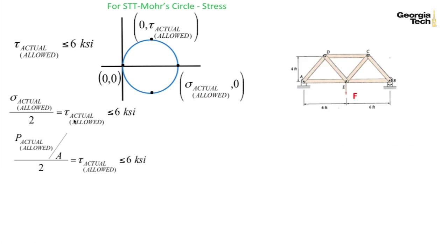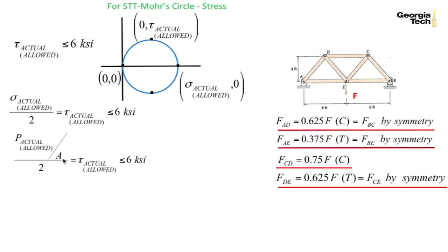Here's our truss. And so for our loads in our members, since these are axial loads, the normal stress is equal to the force in those members divided by the area. I know what the cross-sectional area is because I'm given that in the problem statement. I know what the forces are because I've solved for them. These equate to the P's in any given situation.